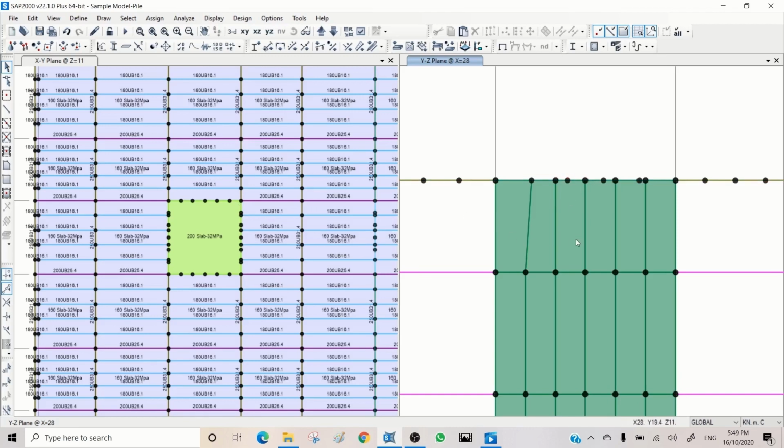The other solution is meshing the shell element based on these points. It's not dividing the mesh like what we did before; it's meshing for analysis. The difference is those are dummy joints, not actual joints. When you add more joints and more elements, you literally increase the size of your mass matrix and stiffness matrix. But when you use this kind of auto meshing, it doesn't increase the size of the file, so the file wouldn't be very heavy and the analysis wouldn't take long. So I can show you what to do.